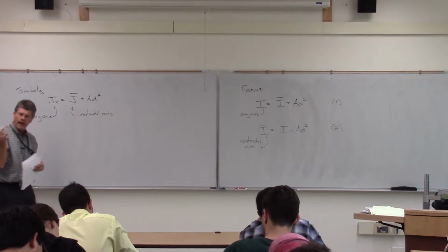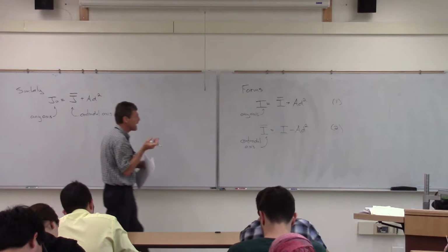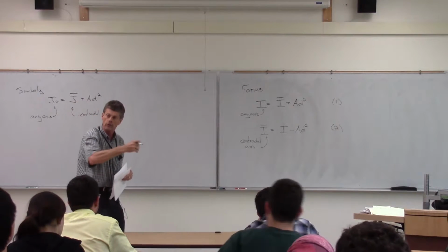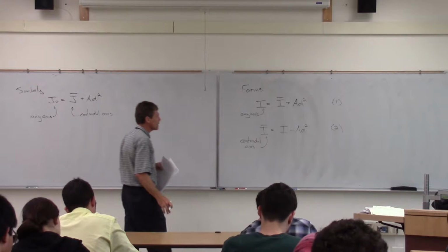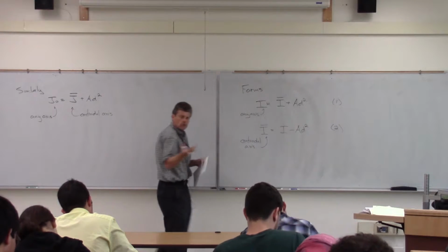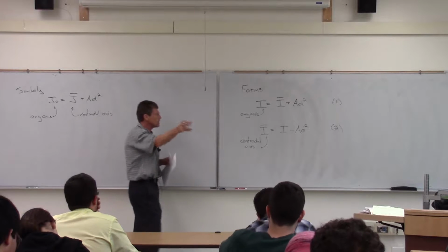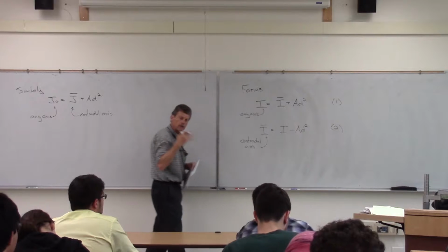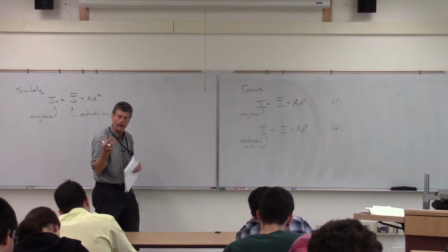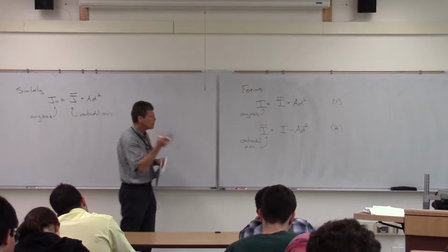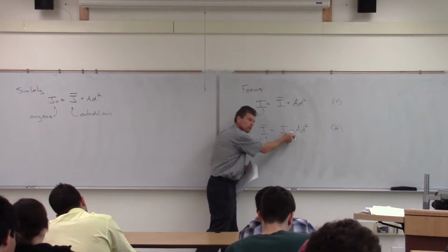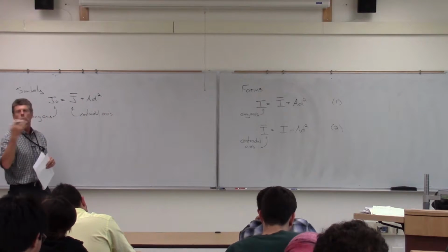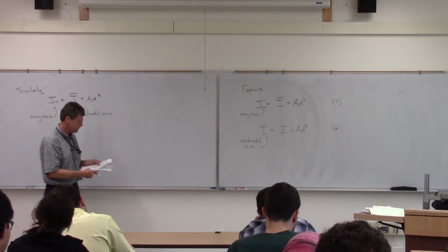And what we can find is that what this form says, then, is if I have a moment of inertia about some axis, and I want to find it for the centroid of that particular section, I can just simply write it the other way. And the point I wanted to make there was the point you made the other day: this is another way of looking at it, the I about the centroidal axis will always be the smallest. We saw that from the integration the other day, but simply looking at it in terms of the parallel axis theorem, any other axis system is going to be bigger than our centroidal axis system.